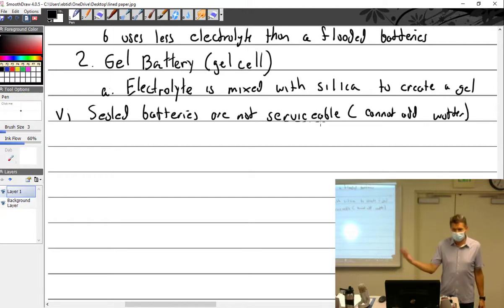So now there's ICAW for everything. I put in a door minder, or door steward, something like that, on my aircraft. It's just a gas strut that, when I pop the door open, opens it up and holds it open on its own. Well, that was a supplement to the type certificate. There are instructions for continued airworthiness.